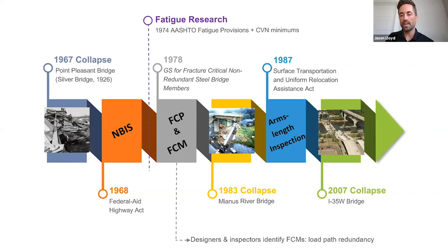However, the collapse was actually caused by a design error that resulted in a buckling-induced failure mode. It was not a result of fracture, nor was it related to FCMs. Yet prominent documents such as the Bridge Inspector's Reference Manual and countless fracture-related papers and presentations continue to incorrectly promulgate it as a collapse related to FCMs.